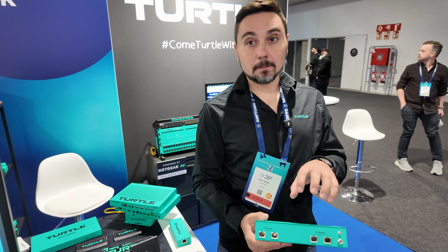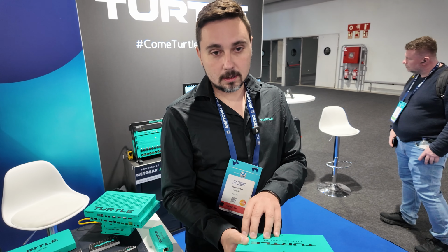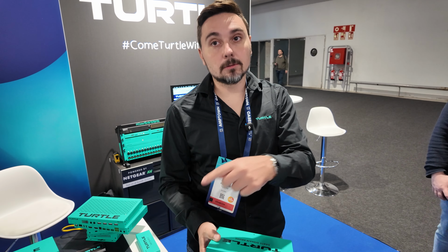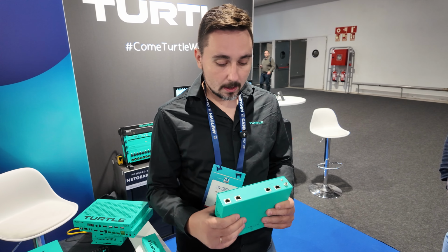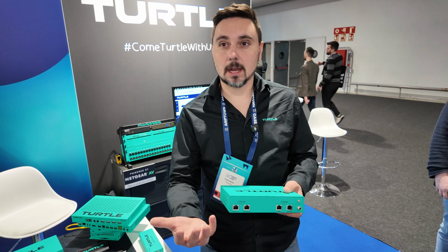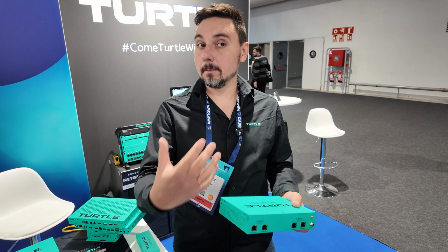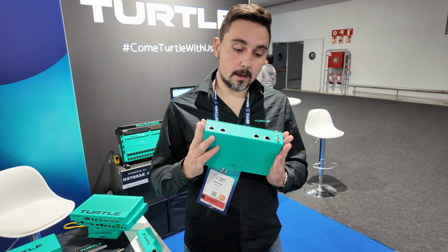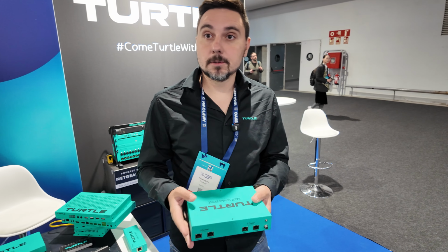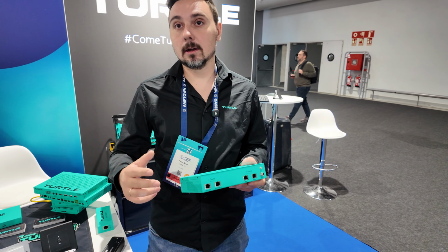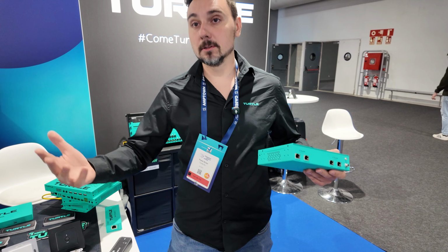I can also do sampling rate conversion, so I can have 96K sampling rate on one side and then 48 on the other, and I can still route channels seamlessly between the two. It has API support. You can change the names of the channels. You can manage your settings through API. It also has web interface. The routing is done via Dante Controller. So you put it on the network, put it on two different domains, and you can seamlessly route audio channels between the domains without exposing them to each other.